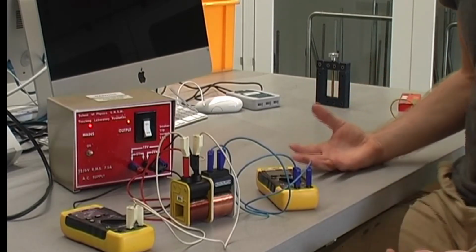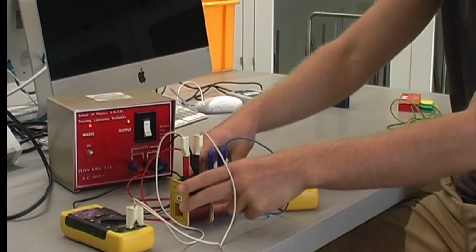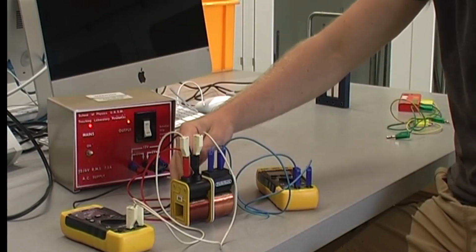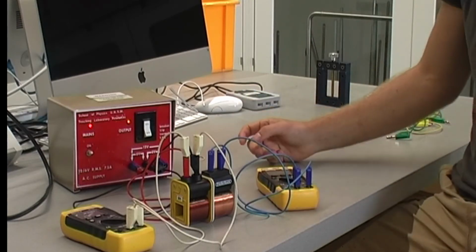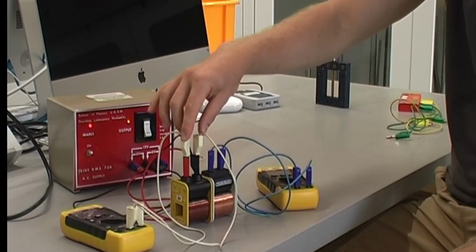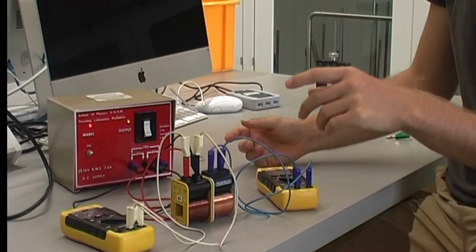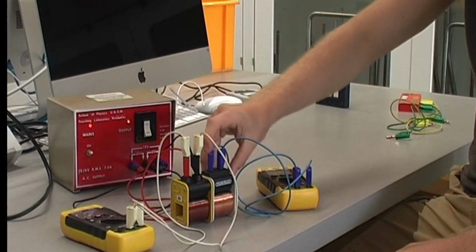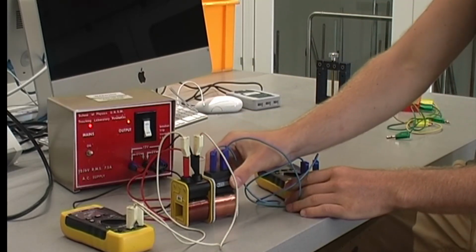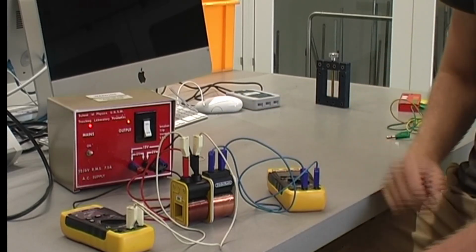Okay, so I'll just show you one configuration for the first transformer you're doing, which is the air core, so there's nothing in between the two. So you've got your power supply going straight into this first coil, which is your primary coil because it's receiving the power. And then we've got a voltmeter that's measuring the voltage coming across the two. Make sure that your voltmeter is set to alternating current voltage reading, which has a squiggly line. And then similarly, you've got a voltmeter attached to the secondary coil. So it's not actually attached to anything, but if you put it close to it, you should see that you're measuring some voltage because of Faraday's law.